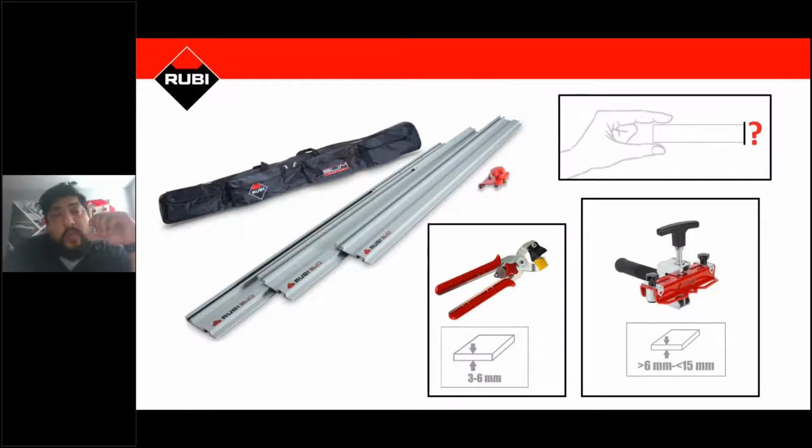The scoring cart, we basically took the technology from our tile cutters with the scoring wheels, and we put it on the scoring cart. And once you use it on the scoring cart, it's like using a manual tile cutter, one of like our TX Max, okay? You just score it, and you want to hear like you're ripping a piece of construction paper, and you want to see a nice deep white line. Once you hear that sound and you look at that line, it's nice, deep and white, you know you got a good score, and you're able to break it with the nippers below.